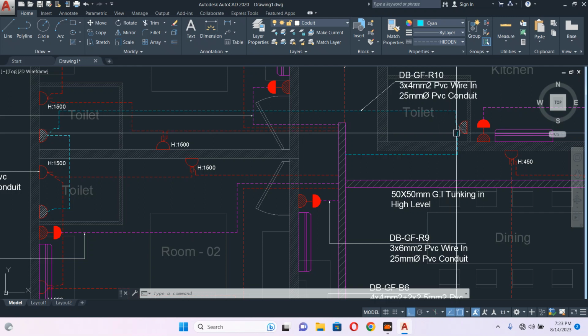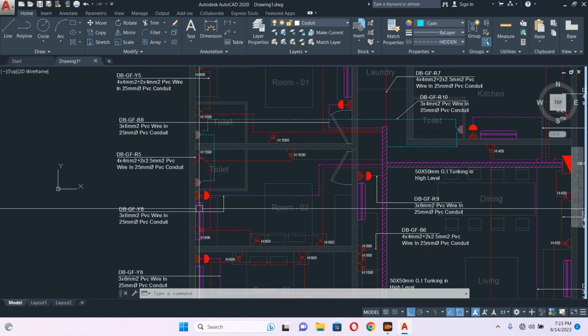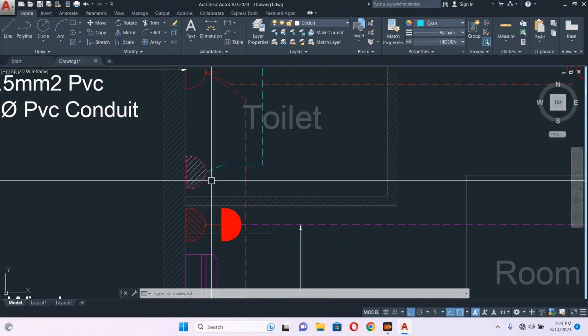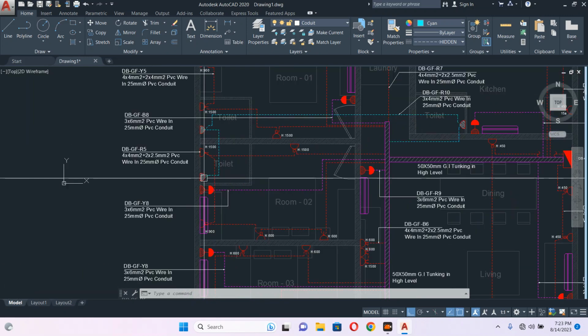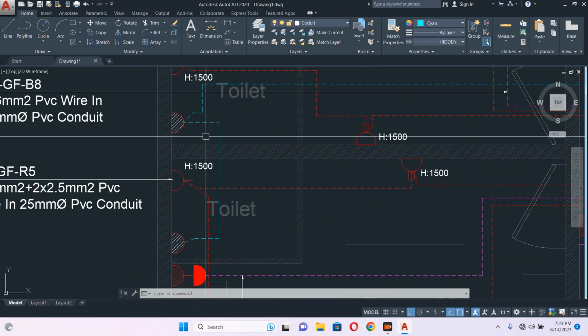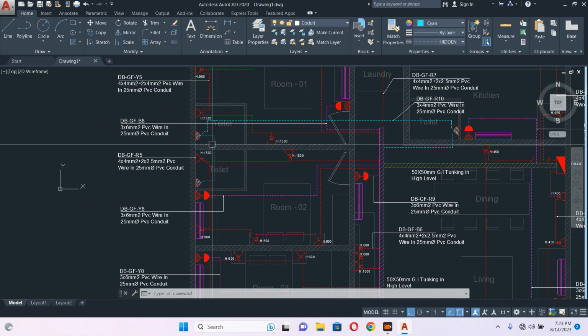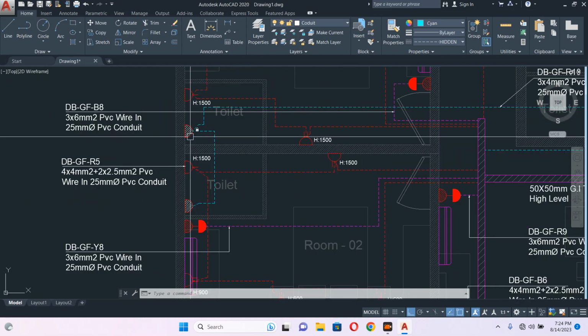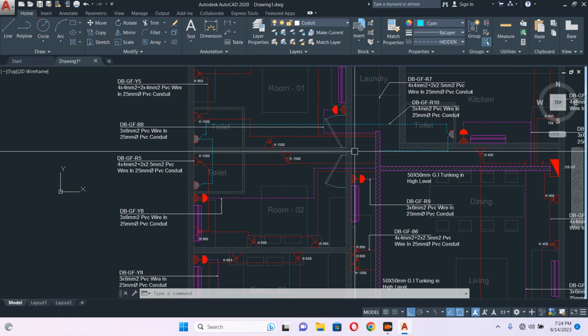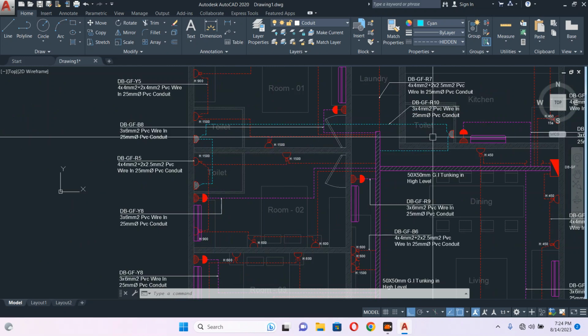So here you have to provide 20 ampere. This spare outlet itself has a small fuse, so even if you use ELCB or not, no problem. But I believe they will request ELCB because it's in a wet area.